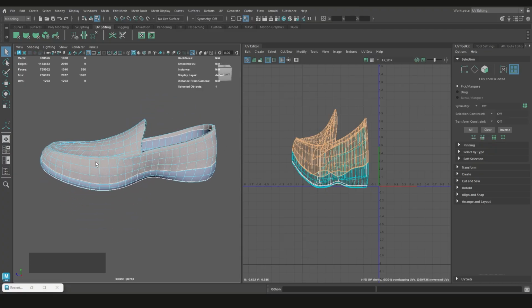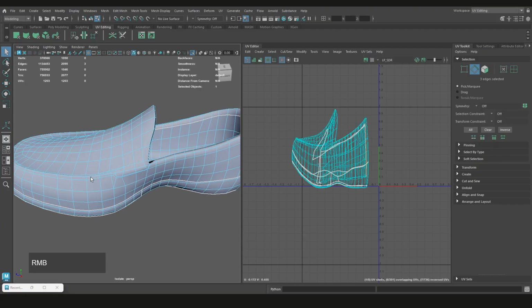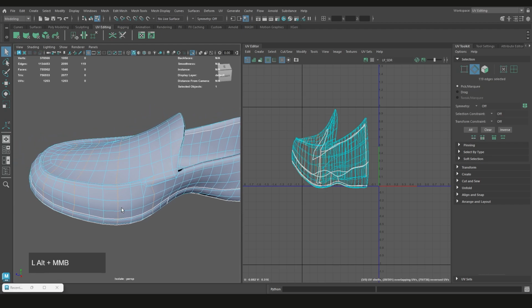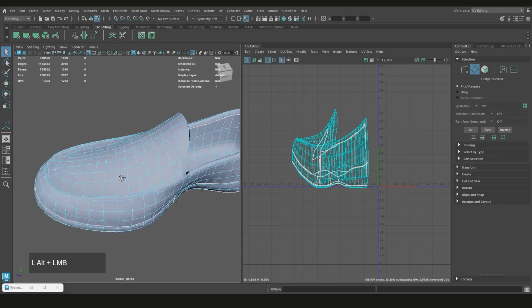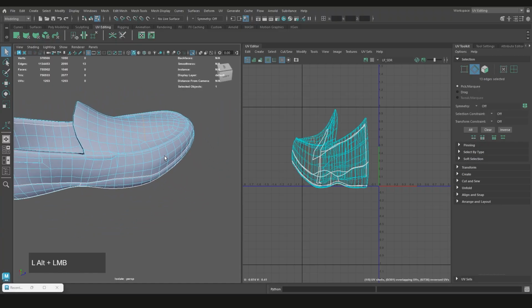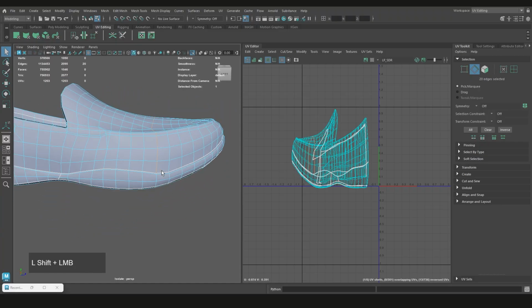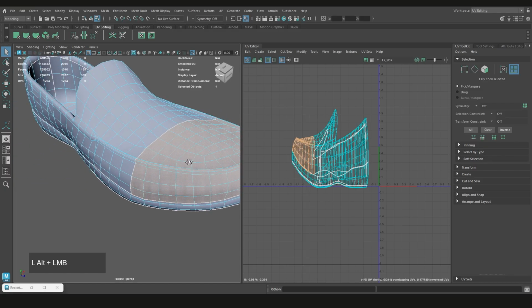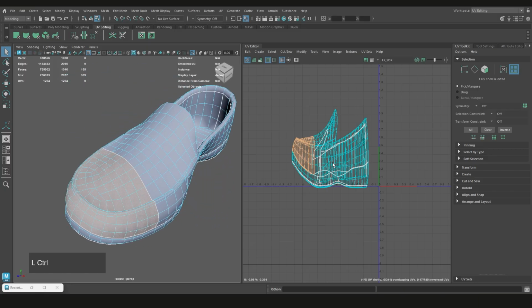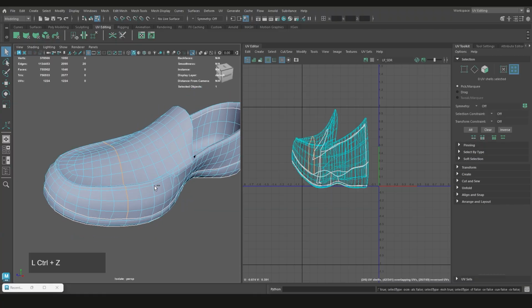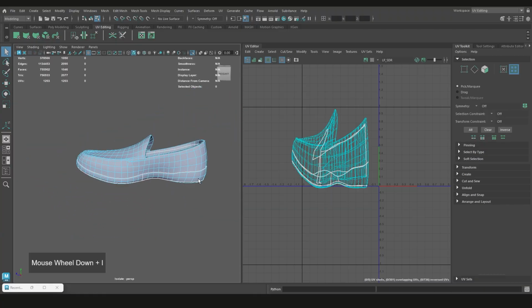If I cut it, let me show you quickly. Let me just go from here to here, right? And then shift click and shift double click. If I cut that, for example, and I go to UV shell and I select this one, that there is going to basically say, oh, that there is a shell, because I cut from there to there. So that's what that's doing. It's basically separating this digitally. It's not literally cutting it, it's just digitally doing that. So we can kind of understand where the seams are for unwrapping.